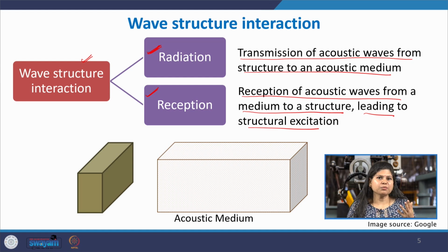One of the mechanisms is through the vibration of the structure. The other mechanism is through fluid flow, such as a stormy wind which is creating sound waves. Suppose we have such stormy wind creating the sound waves, and then suddenly it comes and encounters the roof panels and sets the roof panel into vibratory motion.